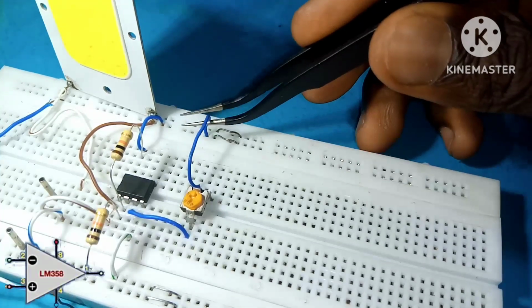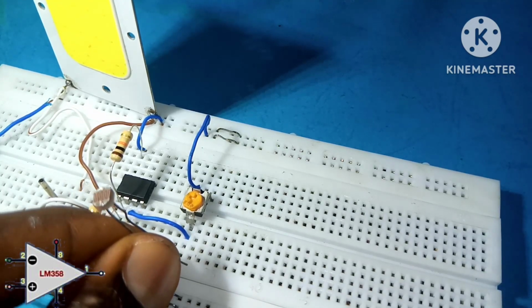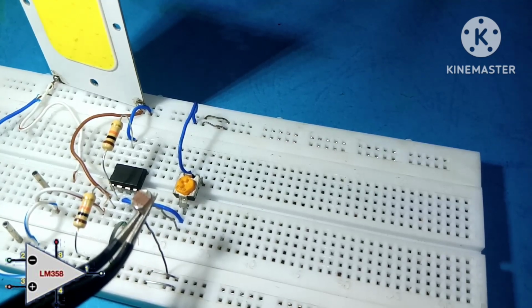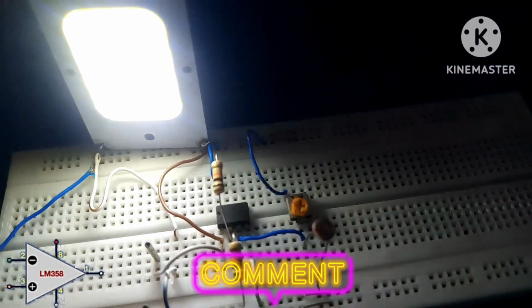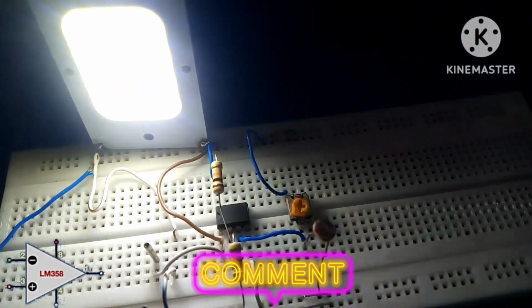So without wasting much time, connect the first lead of the variable resistor to the positive rail, and with your LDR, connect one of its leads to ground and one of its leads pairing with the middle lead of the variable resistor, and hook up your power supply. Right now the light is on because we have room light. When you switch off the light, the LED comes on, and when we switch on the light again, the LED goes off. You can see that.